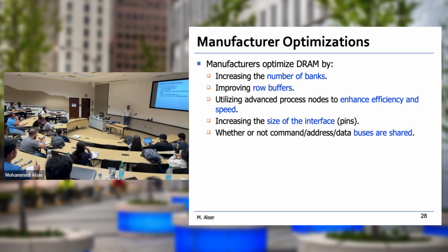Now, if that data does not fit in that row, and your DIMM, for example, is small in capacity, so the rows might be smaller, or you have fewer rows, then you have to access multiple banks or multiple chips or multiple DIMMs to get larger data, right? In this way, you are also losing some benefit or some opportunities to improve the accesses.